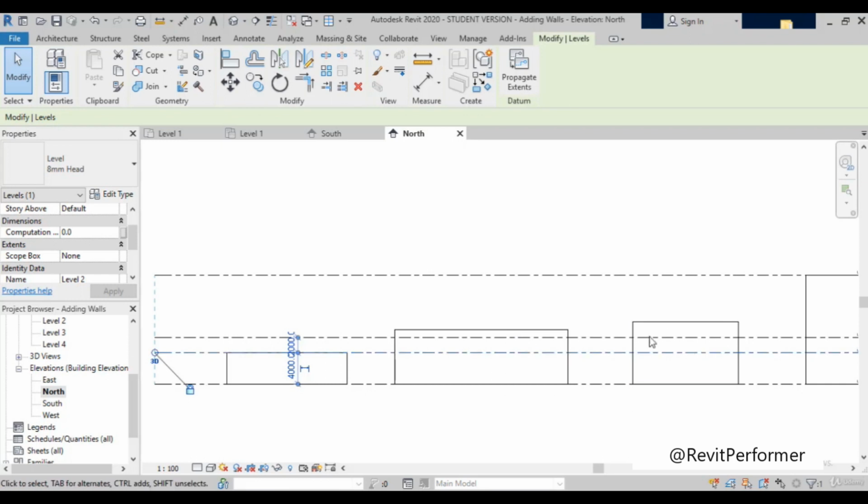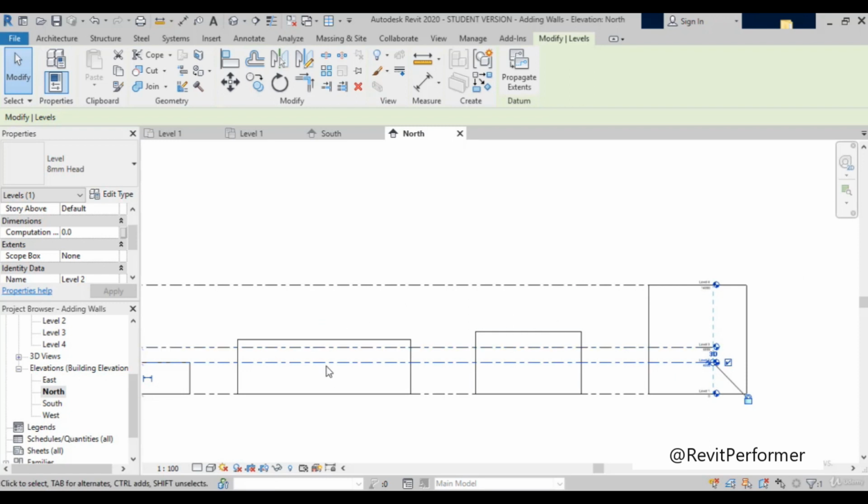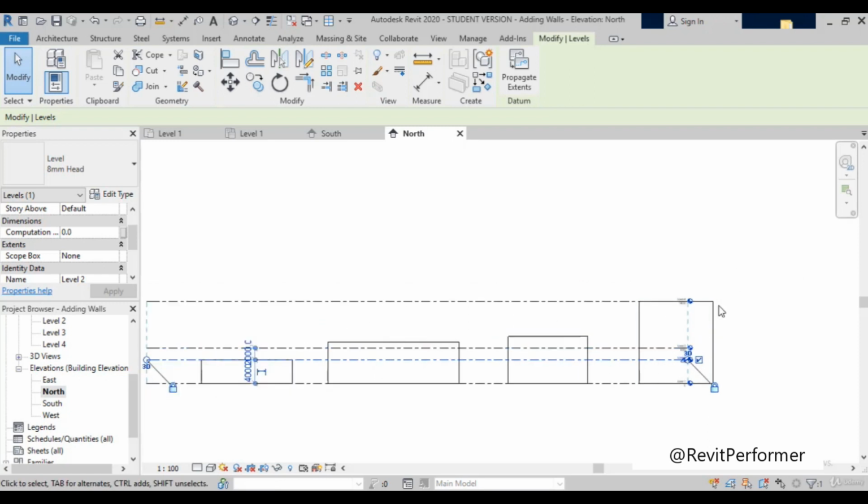If you change the levels also, then it will not affect it. But when you change the levels, the size of this one is affected because it is attached to levels. So this is very important in a top constraint. In the properties panel, if you use the levels for the top constraint, then it will be very effective when you change some levels of the project.